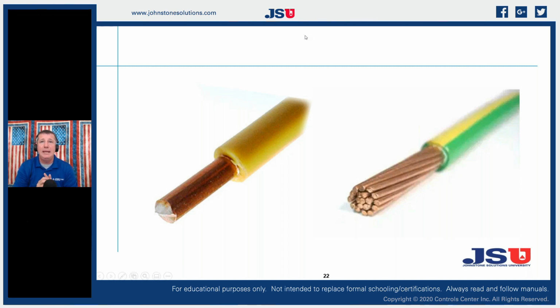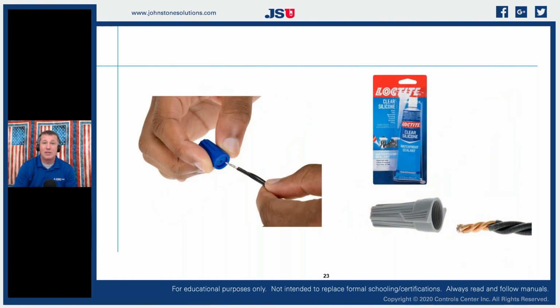So how do we maintain the integrity of our wires, especially when we're splicing? There's a couple things we need to pay special attention to when we are splicing wires that are going to be used for communicating devices. If you're reusing that solid conductor wire and there are wire nuts anywhere along that, you immediately have to cut those off because they've already been exposed to oxygen and moisture. I'll guarantee they're already patinaed and oxidized inside of that wire nut.